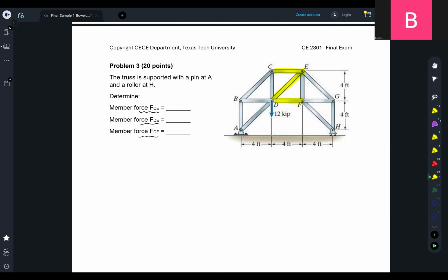It is good if we are interested in the forces in every truss member, or if the truss member is close to the boundary or the edge of the structure. But if we have only a few members of interest and a pretty big and complex structure system, then approaching it by method of joints will be an extremely long process.